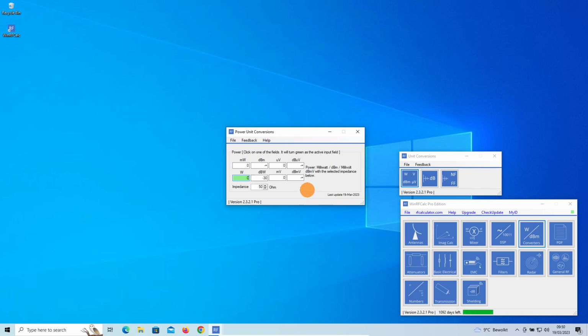Now, let's go back to 0.02 watts or 20 milliwatts. So it gives you 1 million microvolts, 1000 millivolts, 120 dB microvolt, and 60 dB millivolt. Now, if we change the impedance to a value of 200 ohms, which is 4 times more, and starting with a power level, then if we change the impedance, the voltage numbers are going to be recalculated. So let me show this to you.